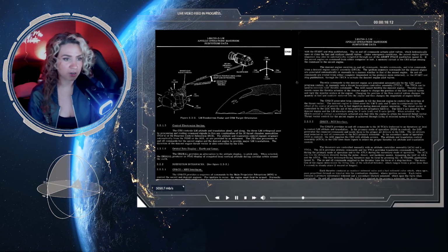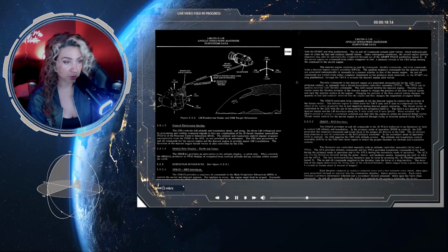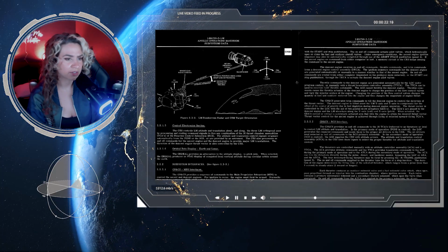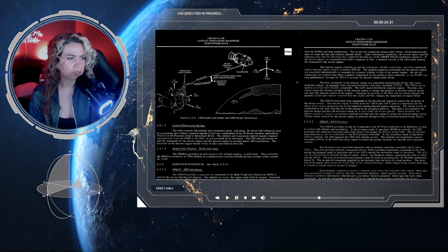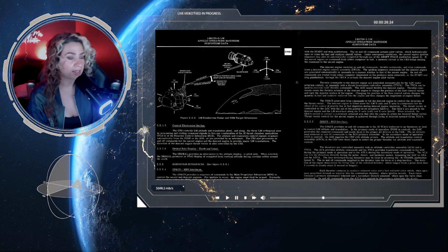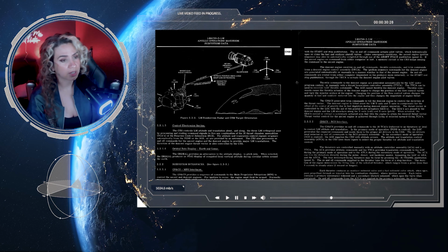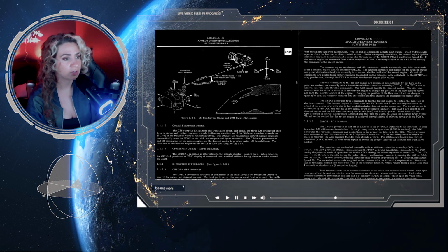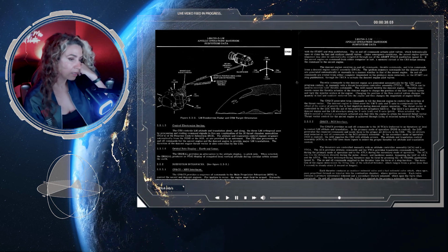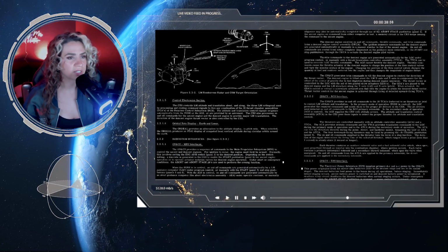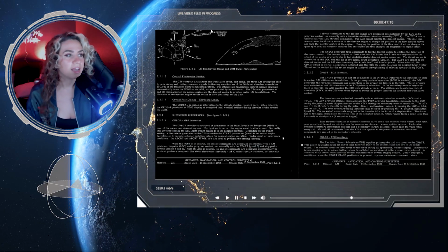In the secondary mode of operation, AGS in control, the AGA supplies the CES with attitude errors. The Attitude and Translation Control Assembly, ATCA, in the CES uses these inputs to select the proper thrusters for the attitude and translation control. The thrusters are controlled manually with the Attitude Controller Assembly, the ACA, and the TTCA.